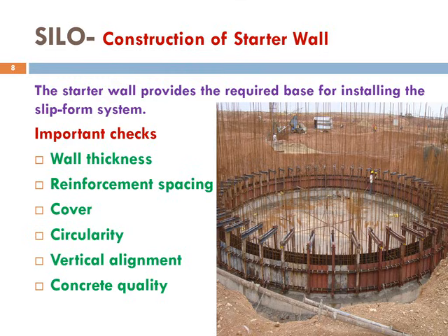The starter wall is an important part of silo construction. It provides the required base for installing the slipform system. Before proceeding further, several important checks must be completed. We must check the wall thickness because the wall must have the design dimensions. Reinforcement spacings must also be checked carefully.